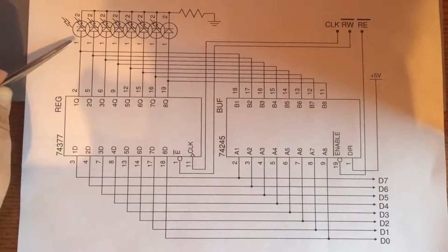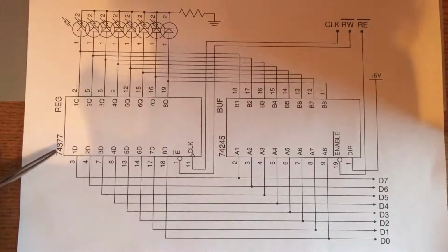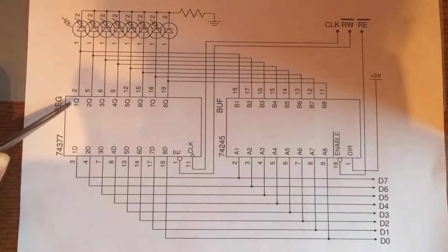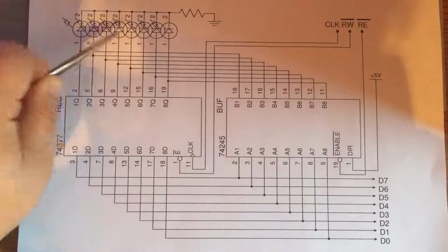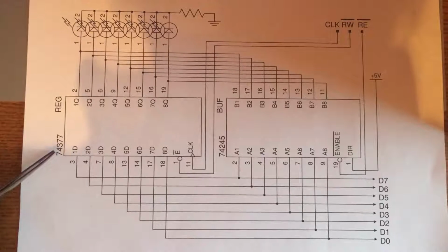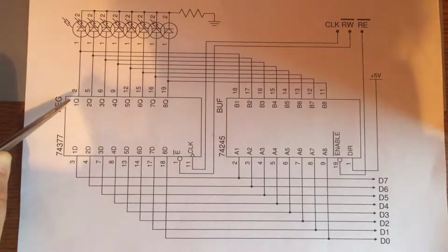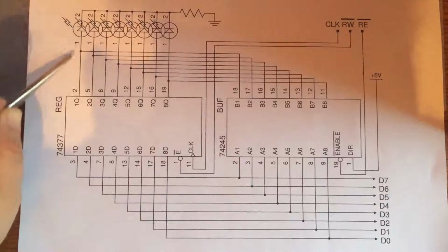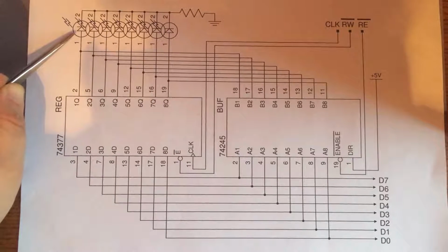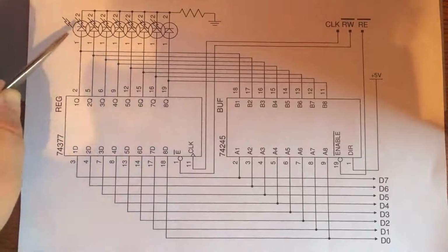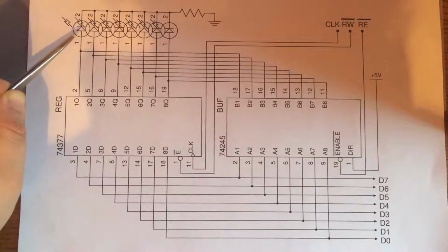That also is a slight difference compared to Ben's computer, because Ben is using the 74LS series of chips. They actually have some pull-down resistors built into them. For whatever reason, in Ben's case, those pull-down resistors work fine and they limit the current in a way which is sufficient for his design. However, I noticed that with my HCT series, when I connected an LED directly to ground, without this resistor, I was drawing an awful lot of current, between 40 and 50 milliamps for each LED. If I had 8 LEDs, all drawing 50 milliamps, that would be 400 milliamps just for one register.